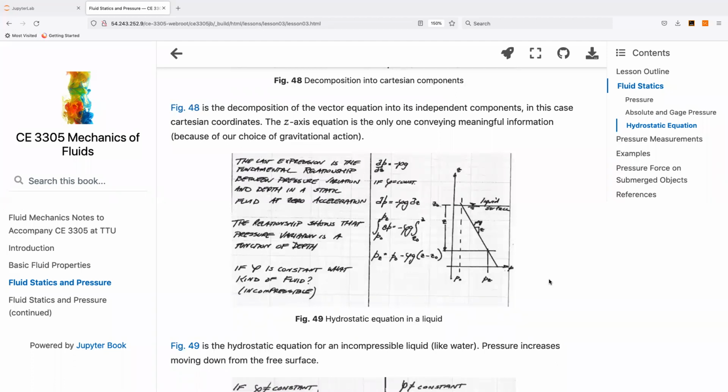So as we're going down, our pressure is increasing. We get to whatever our depth is, and that is the pressure we experience. In this case, P sub Z versus P sub Z0. And then if we move back up, we follow the slope of that line. This axis is representing pressure. There's a little bit of calculus to show you how to calculate it. Normally, it's pretty straightforward. Pressure goes up when you go down in the fluid. It goes down when you go up in the fluid. And presumably, you know where the free surface is, and the pressure at the free surface is 0 gauge.